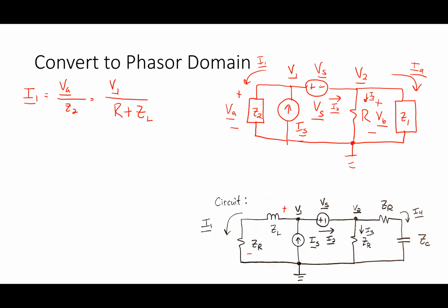Because I don't have an Ohm's law that I can write for a voltage source. The voltage source just takes whatever the circuit tells it needs to take. So there's no way to make a relationship that constrains the voltage and the current. If I have an impedance, then there's a constraint linking the voltage and the current. There's no constraint for a voltage source.